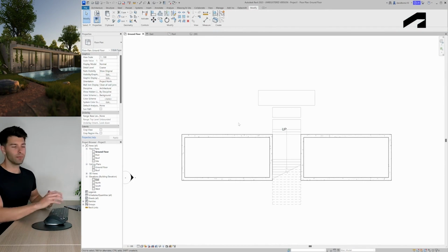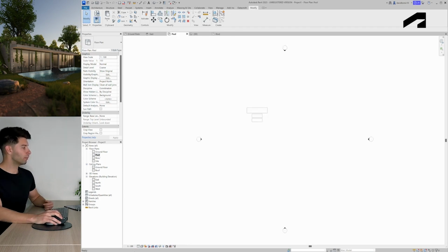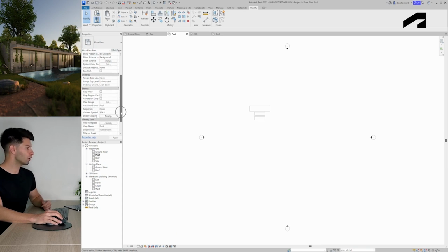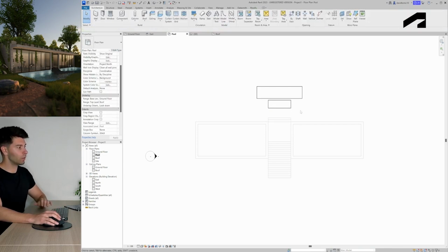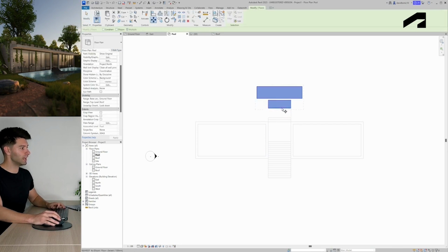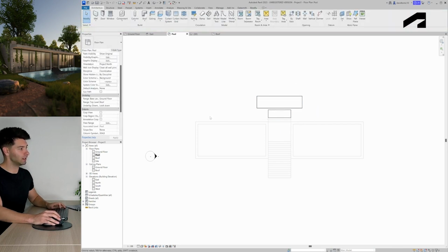to life. So now let's jump back into our floor plan and make this pool with a nice curved front, natural organic edge. If we double click on our pool plan, we're gonna see a couple elements pop up, and that's okay. Instead, we're gonna come to our left-hand panel up the top, scroll down to our underlayer and select ground floor. Now that we have our ground floor underlaid so we can see what's going on, personally, I think there's 1 too many stepping stones. So let's delete one of those stepping stones, select all of these, and then push it back to create that landing. Otherwise, that pool is just gonna be way too big and completely out of proportion.